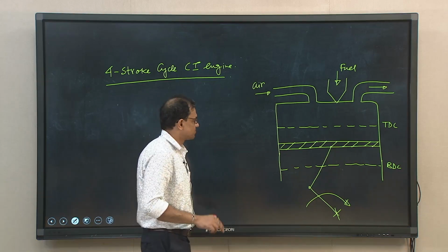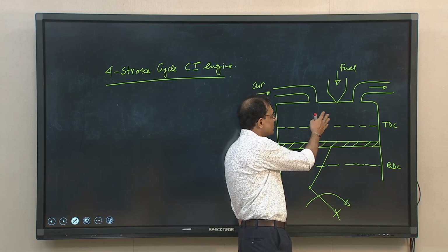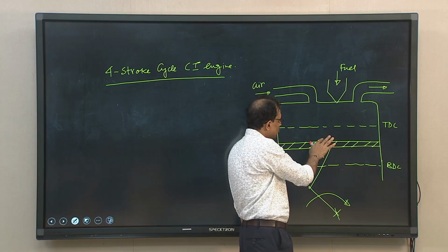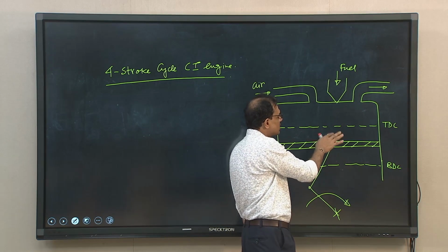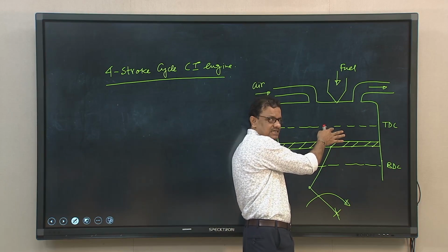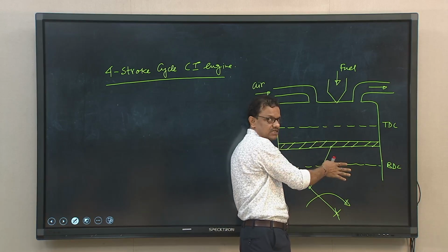So, late phase of combustion. Considering all these, it is not possible to mimic the combustion by a constant volume process, because combustion will start when the piston has not even reached TDC, combustion will continue when the piston reaches TDC, and it will last even when the piston is leaving TDC towards BDC.